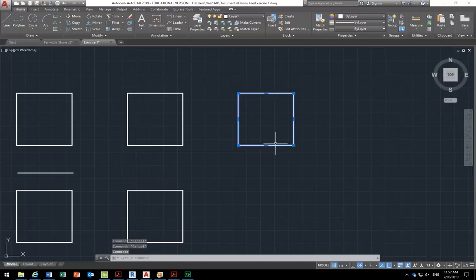So if I select that square or rectangle, then you've got this tool here, Explode, which we're going to look at later. Click on that. Now they're lines. It's just like I've drawn it with the line command. Yeah. And can you do the opposite? Can you do the square you've drawn the line? Absolutely. And group it? You can. Yeah, it's a bit more involved, so I'll show you that later. But yeah, of course you can.